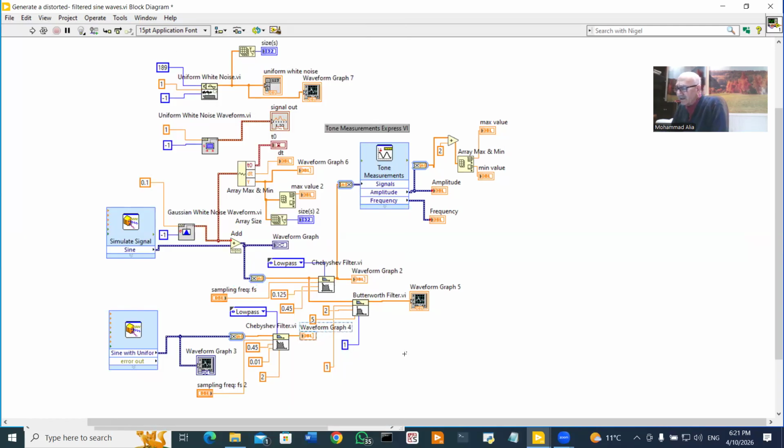One more thing, I have shown you how we can use the Butterworth filter as a first order or as a second order, and a little bit the difference between the performance of the Chebyshev filter and the Butterworth filter, and we have got the output as different waves, but either of them is now clean comparatively with the input.